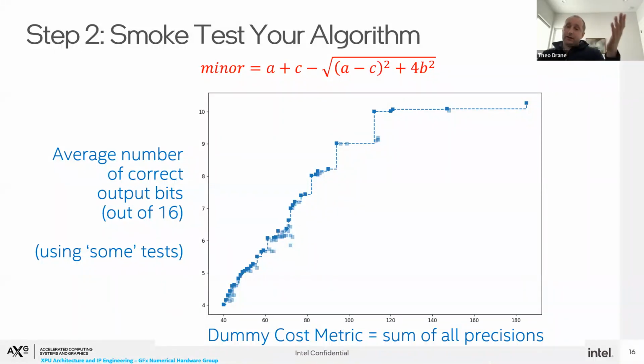One of the lovely things about this is that if there's somewhere in your data flow graph that needs more precision, this will find it. So you clearly have that area where it will automatically do what people have been doing by hand, like this variable in the middle of your algorithm is very numerically sensitive. You'll need more bits, and this will automatically find it. But similarly, by changing what goes into this search, you can choose between algorithms, you can conditionally choose, you can ask a whole range of different questions that is actually architecture design.